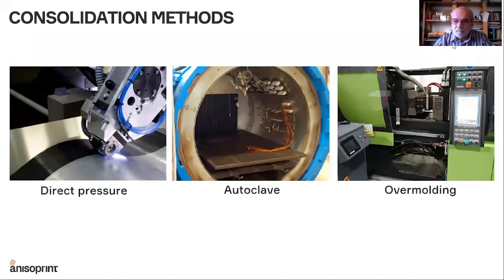It will require dedicated machinery like an autoclave, and still the pressures can be quite high, and complex 3D shapes might not be able to consolidate. Especially, you can do the consolidation between the layers, but if you need to consolidate between the fibers, then it might be quite difficult to do in an autoclave, because fiber will not allow the material to shrink.